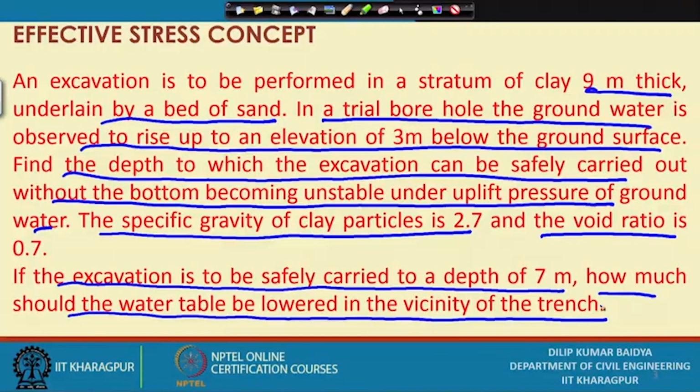So, a 9 meter thick clay layer, below that there is sand, and the sand layer is under pressure. And how much pressure? When we make a borehole, we will see the water, how much height it has risen. So, that is what is shown. The water table is actually shown 3 meter below the ground. While excavating through the clay layer, which seems highly impermeable, it is not showing water table, but when you puncture that, go to the sand and make a borehole, we will see the water table up to 3 meter below the ground surface.